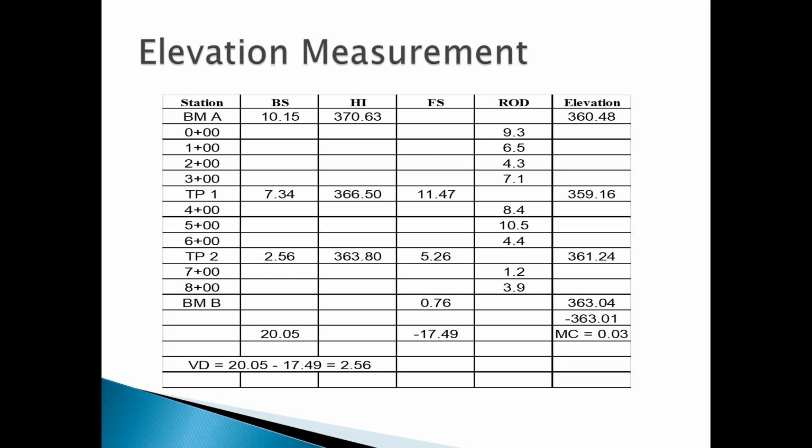So once you do this and you know that you've got good HIs, okay, and again, a lot of people I noticed mess this up. This HI is used to calculate all of these. So you're going to store that number minus 9.3, that number goes here. That number minus your HI goes here. This number minus your HI goes here.